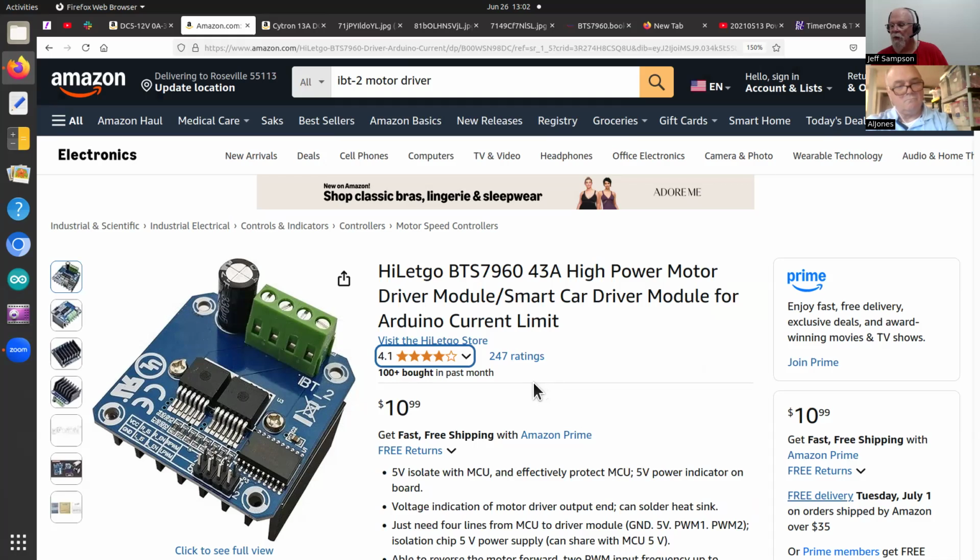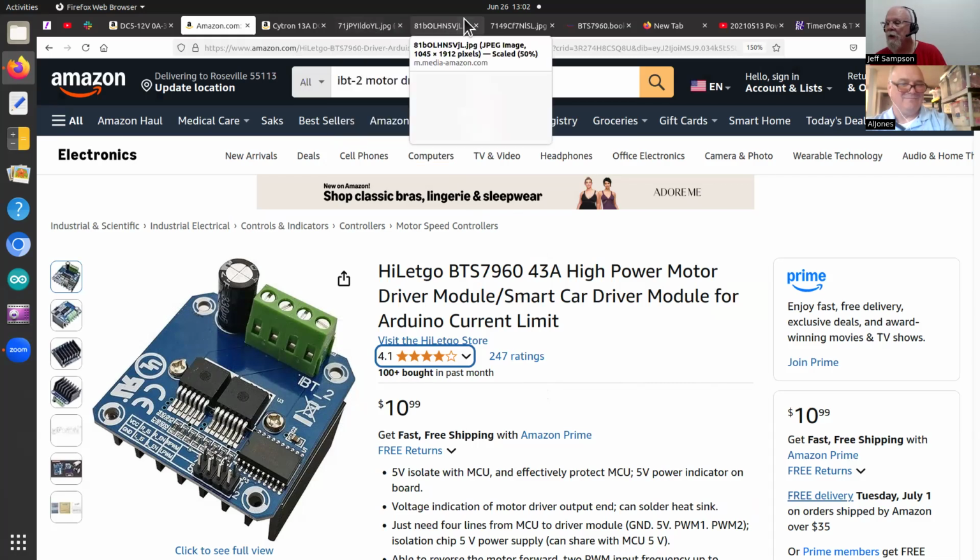And then, as I say, that's when I ran into the thing about if you run the AnalogWrite as opposed to TimerOne, you can either make your motors squeal and play music or keep them nice and quiet. Was there anything else on that? Let's leave that for this week, and then I'll move on to something else here.